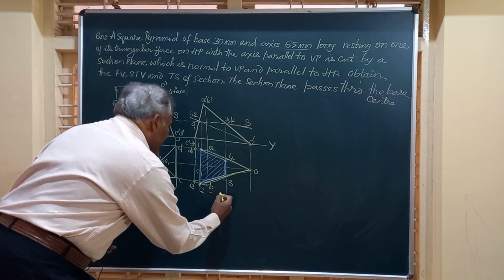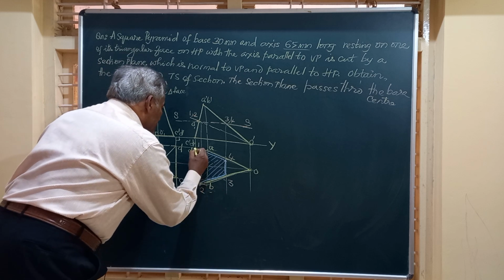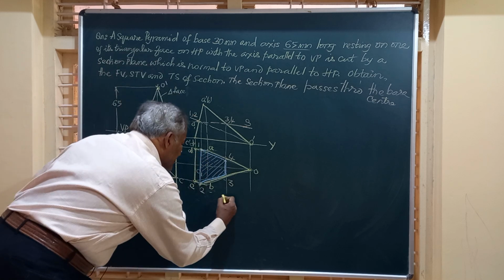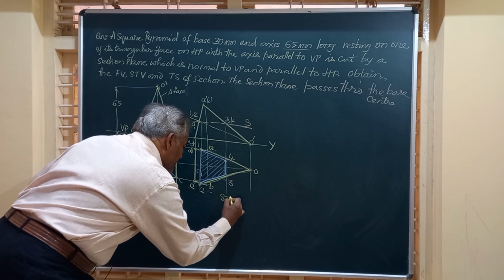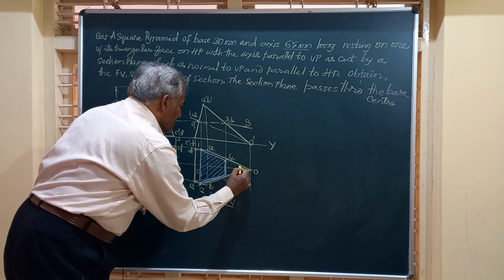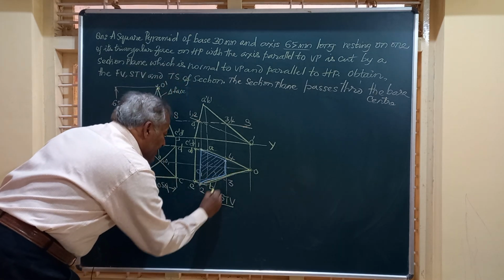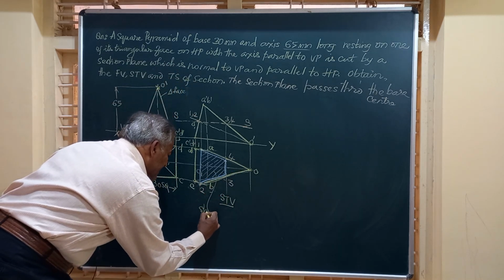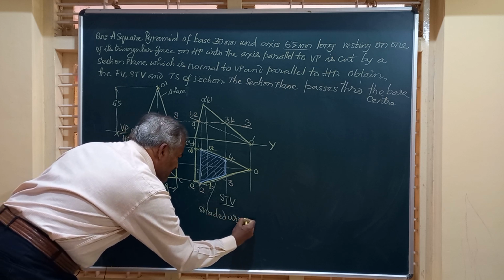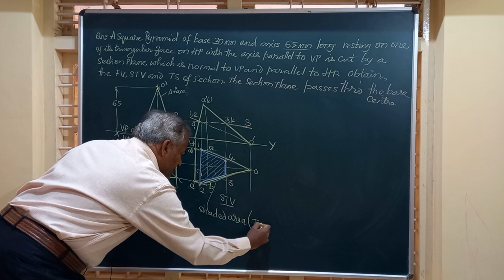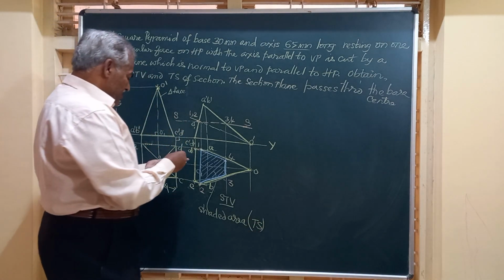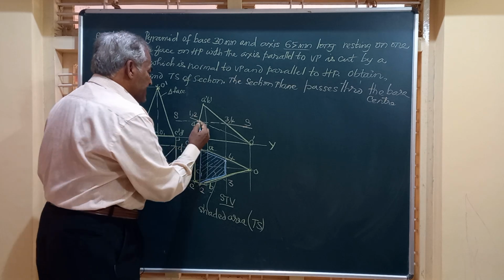So this figure, friends, the total figure is the sectional top view because it is shown hatched, and this shaded area is the true shape of the section. So the shaded area becomes the true shape, and here we have to darken the portion that is retained.